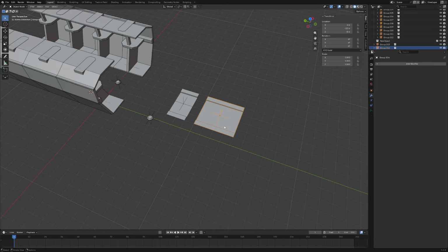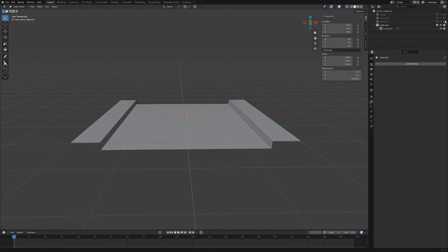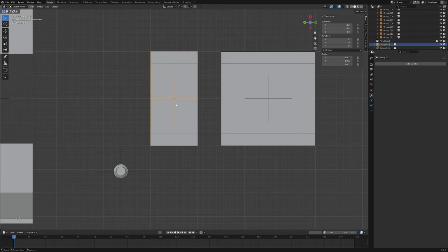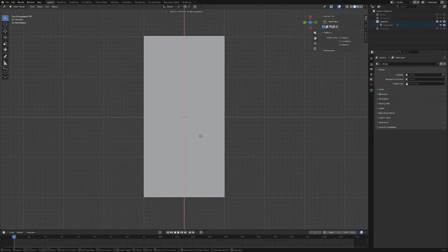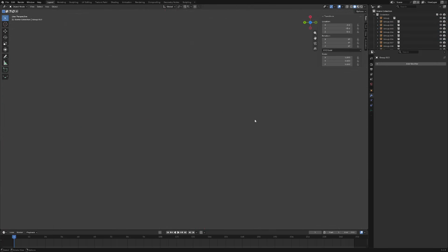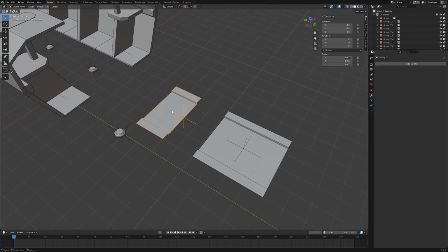You can just hit the tab key. When you're in object mode, you hit tab, usually it goes into edit mode. But when it's a collection instance, it takes you to that scene and lets you work on just that asset, and it isolates it too. So we could have done that over here like this. So for example, if this pivot point is not the way we want it, we could just move it here now after hitting tab. You go to the empty space, make sure nothing's selected and hit tab again. It goes back to this one over here. Okay, so you can get in and you can get out basically.